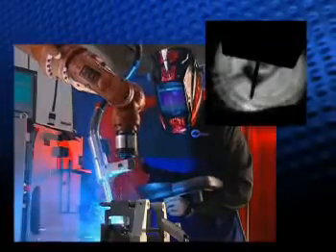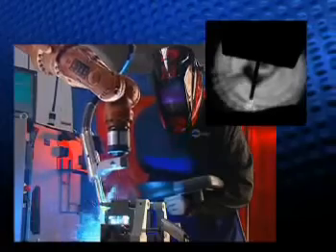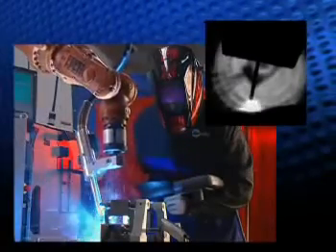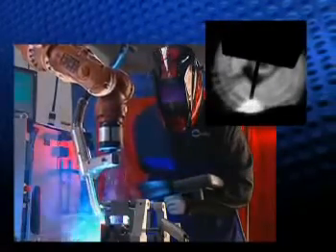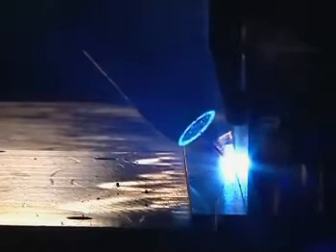In pulsed spray transfer, the power source rapidly switches the welding output from high peak current to low background current. The peak current pinches off a spray transfer droplet and propels it toward the weldment for good fusion. The background current maintains the arc, but is too low for metal transfer to occur. With no metal transfer, the weld puddle gets a chance to cool.